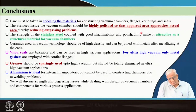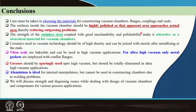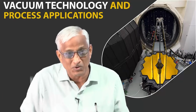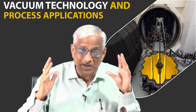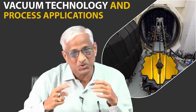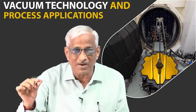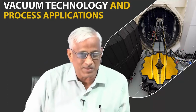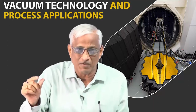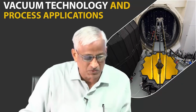So, we will discuss these degassing issues when we go to vacuum chambers and various process applications. If it is a chemical or pharmaceutical application, we may not bother about outgassing from the surfaces. We have to bother about materials that will not be attacked by these chemicals. So, depending on the application, you have to choose the material, but finally it is only a 1 bar pressure difference, not much. So, mechanically, if you make the design following ASME codes for an external pressure vessel with 1 bar atmospheric change, it is good enough. And if you want to reduce the thickness, use stiffeners outside.